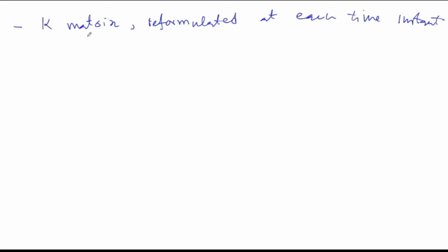The problem with their solution is also that the response of the various modes is coupled. So remember that in a real nonlinear dynamic time history analysis, the response is coupled. All modes are coupled. So you cannot just idealize, let's say, a building with one mode and analyze it only for that mode and expect it to give a correct answer. But in fact, all the modes are coupled. And we will see in the coming slides that in the elastic response, they are mostly uncoupled, and you can divide that problem into a number of problems, treating every mode separately. But in the case of nonlinear behavior, we will see that you cannot treat them separately. The higher modes depend on the initial modes.